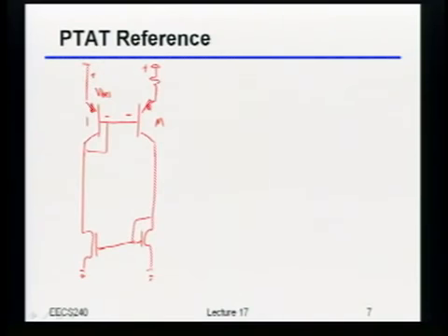Yeah, it also has to be VBE1, right? Okay, so if that's VBE1, well, we also know that, of course, from there to there is VBE2, right? So if that's the case, what's the voltage that shows up across that resistor there? The first one. Yeah, it's the difference between them, which I'm going to call just delta VBE.